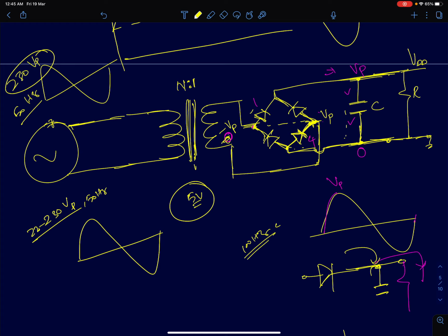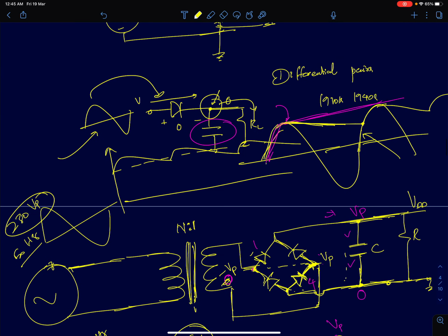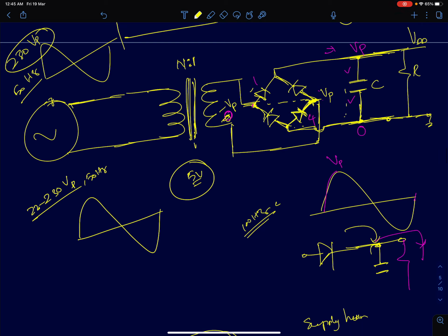and the value of the AC voltage will also be different. So this signal is first converted. If you look at the peak detector circuit, the peak value that this can go to is simply equal to the peak value of the sine wave. So I need a peak detector circuit to convert a sine wave to a DC signal, but the peak of that sine wave which I am going to feed to the peak detector should be equal to the DC value, or close to the DC value, that I need to generate. I need to convert a 230 volt peak signal to a 5 volt peak AC signal.